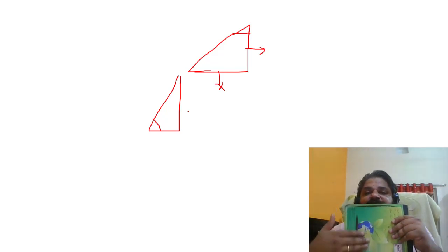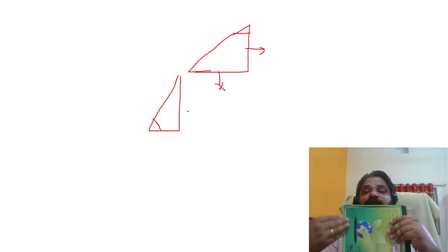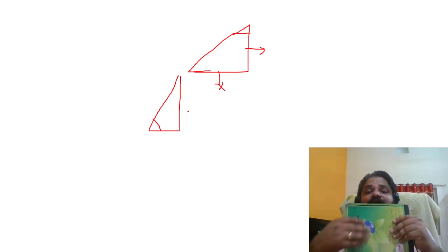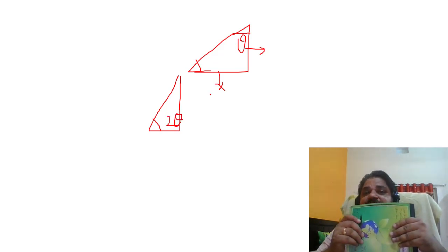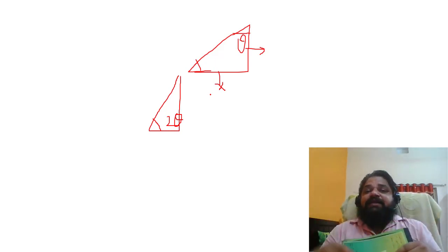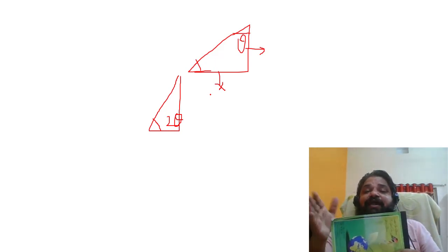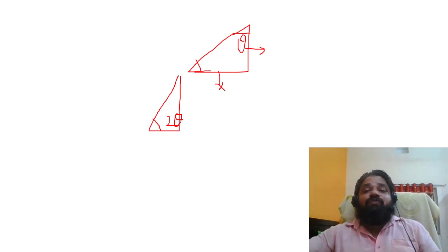If it is on a single plane, then sigma x and sigma y, which are mutually perpendicular to each other at 90 degrees, when I open it, they are shifted to a 180-degree difference. So the angle which started with theta, or this 90 minus theta, is now converted to 2 theta. That means the mutually perpendicular planes have now been separated. Instead of theta it is 2 theta, because instead of 90 they are at a distance of 180 degrees. So this is the main concept behind it, and based on that it has been calculated.